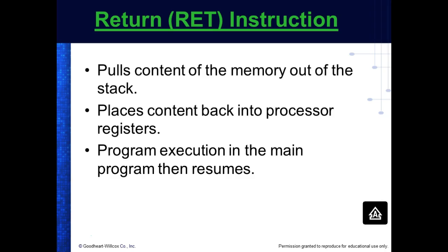Here we're dealing with ladder logic. The last instruction that occurred before the JSR, it saves everything that was going on. If it's a math instruction, what would it have to save? All your accumulators, right? Your source A, source B, all the general purpose registers, all your flag registers, to know if it had an overflow or whatever. It pushes that onto the stack, and then it goes out and runs the subroutine.